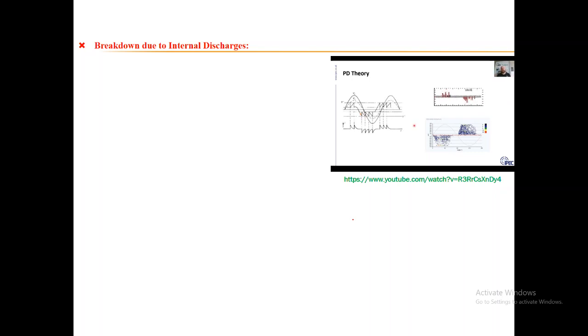So on the right hand side is images that people might be quite familiar with. This is called a PRPD, phase resolved partial discharge, and it's PD patterns in the power cycle essentially. It's one of the tools that is used within a lot of PD equipment, within a lot of instrumentation, to help you decide if the signal you're seeing is from a genuine PD source or from a noise source. It's this distinctive pattern.